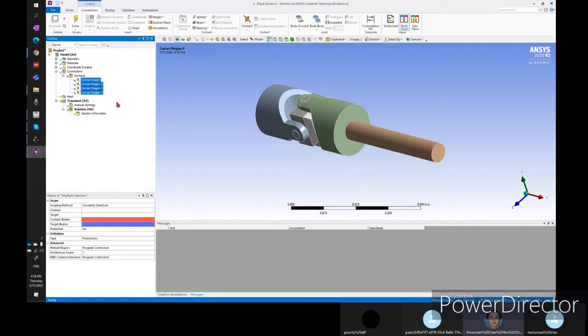When you want movement or motion, the contact regions either need to be very specific, or actually are not needed at all. Basically, it is the joints over here that help us define our assembly movement, or the mechanism of our assembly.